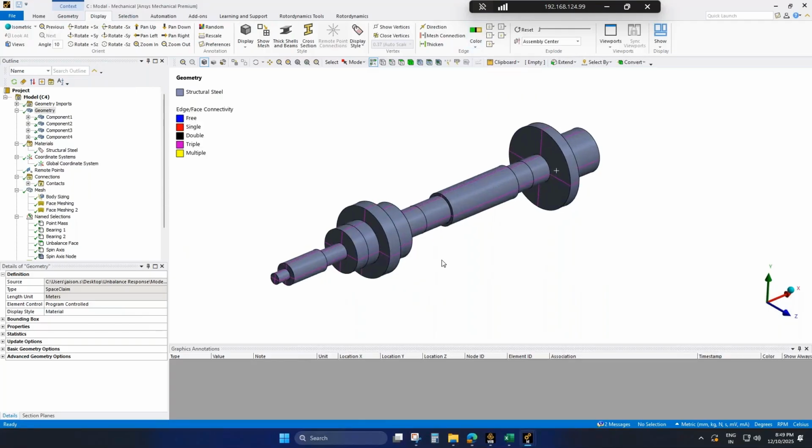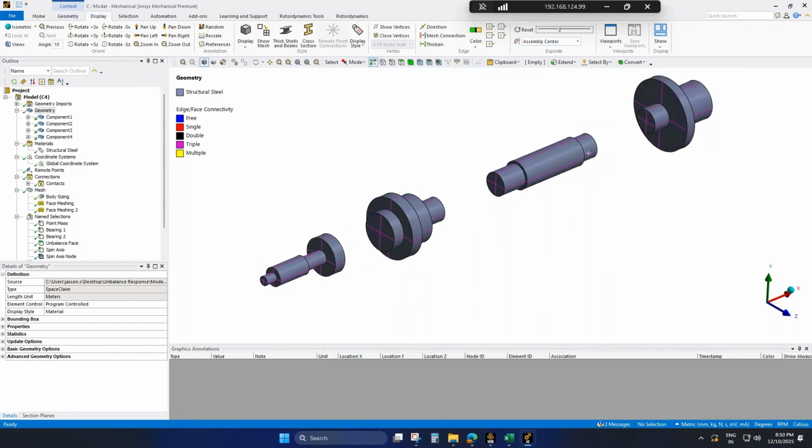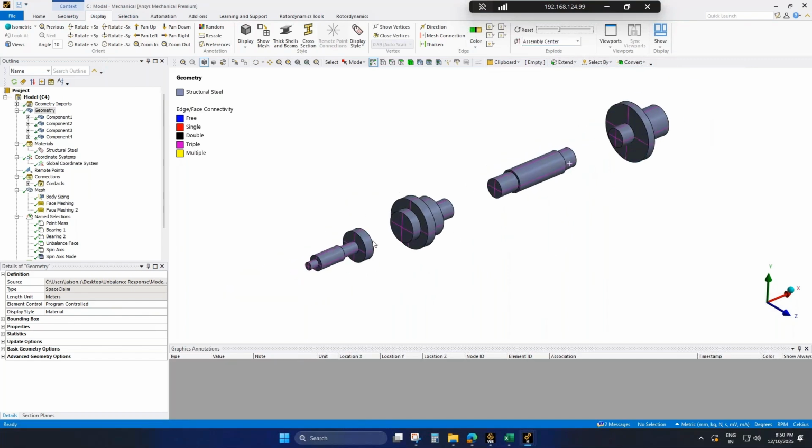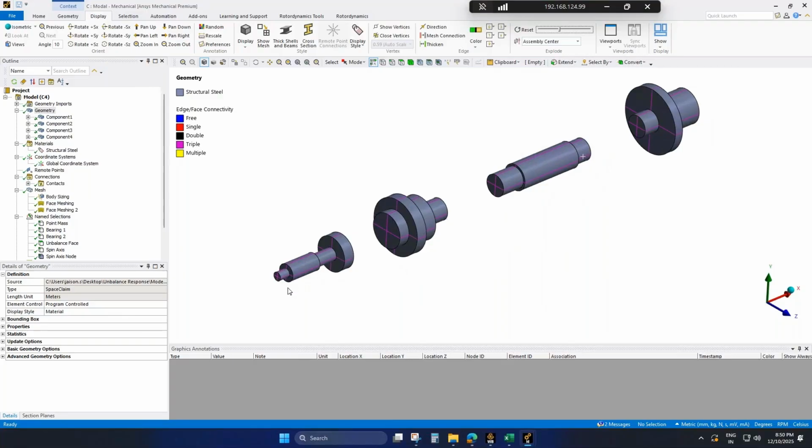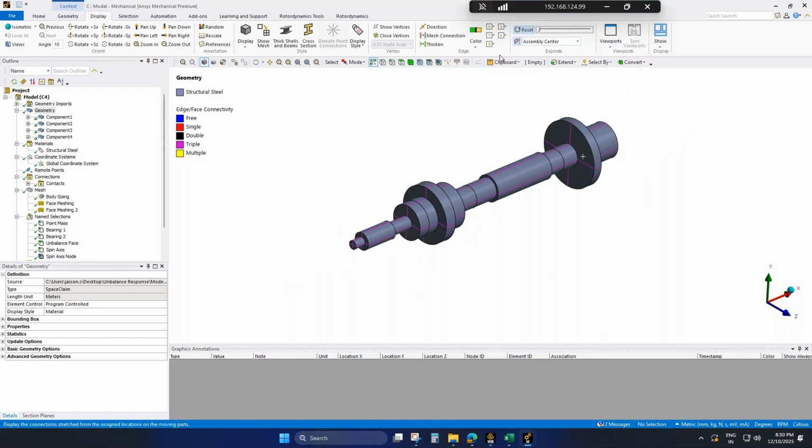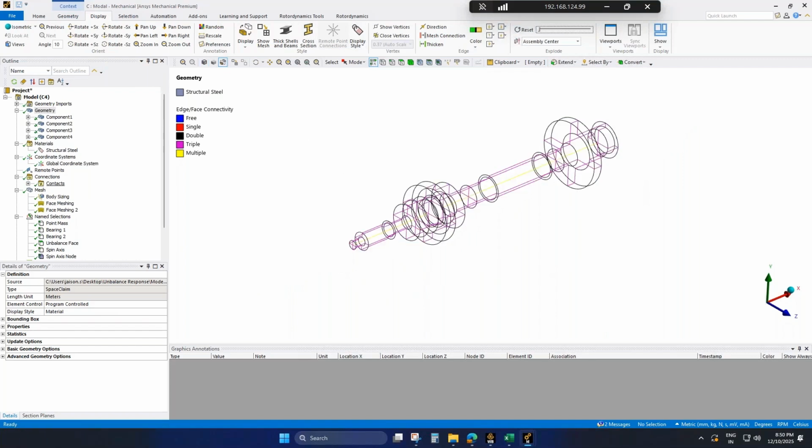We have split the rotor into 4 parts, and there is also a shared topology option to get coincident nodes on the common face of the two bodies. This has been done so as to get a common node at the spin axis, right? We will see the spin axis if we reset the exploded view and turn on the wireframe mode.